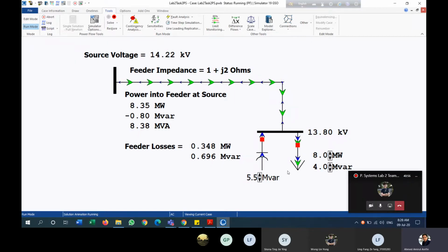If I just make it similar, 4, then in the load our requirement is 4 MVAr of reactive power, and my capacitor is also supplying 4 MVAr. So the MVAr losses should be the minimum, where you can supply the load requirements and your losses will be very low.